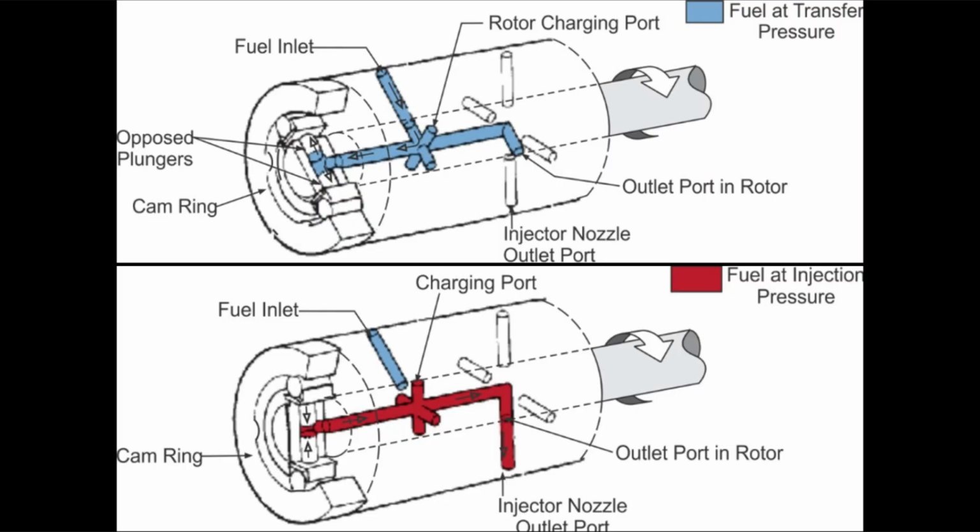And the amount of fuel that's metered into the pumping chamber also depends on the metering valve's position, the transfer pressure, and the amount of time that the inlet and charging ports are aligned. This entire dance represents the charging, or the loading action, of the pump.